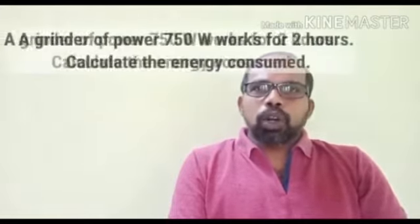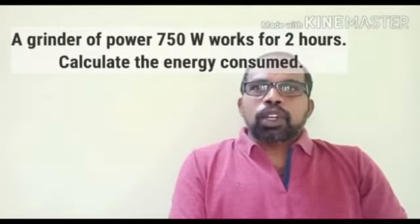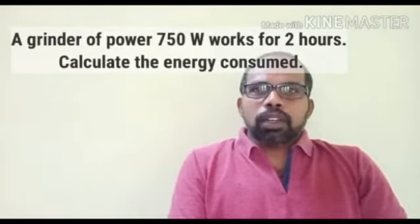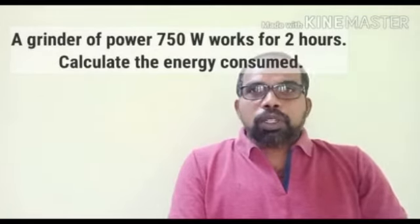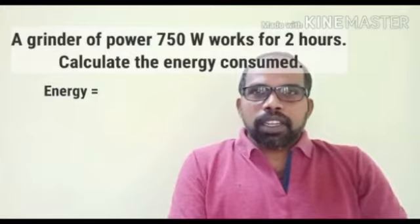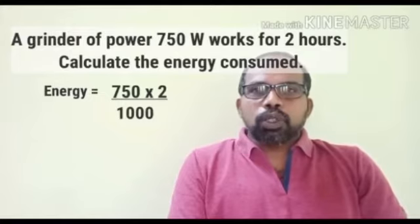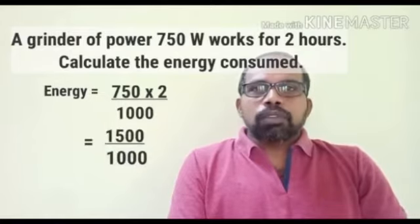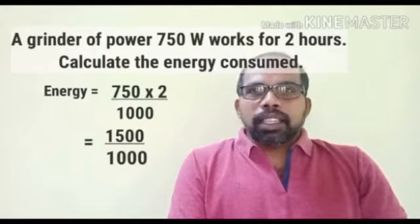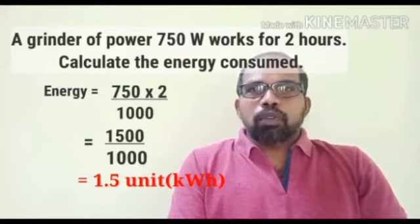So let us solve this problem. A grinder of power 750 watt works for 2 hours. Calculate the energy consumed. So in order to find out the energy in kilowatt hour, you have to use the formula power in watt into time in hour by 1000. So here power in watt is 750, time in hour is 2, by 1000. So 750 into 2 by 1000, that is 1500 by 1000, that is 1.5 unit or 1.5 kilowatt hour.